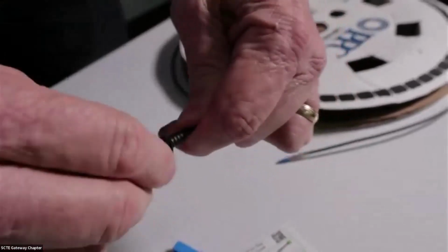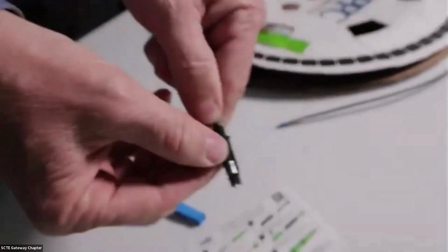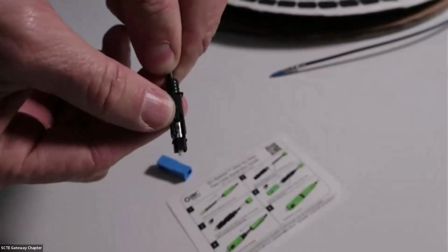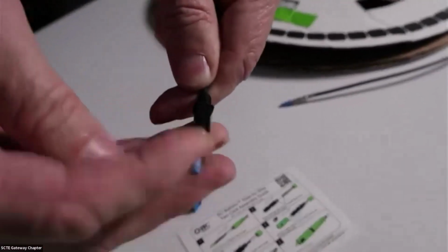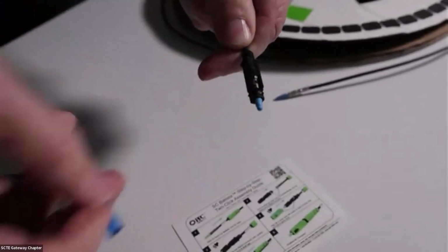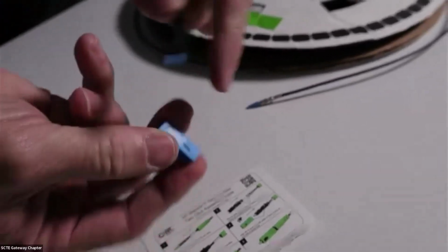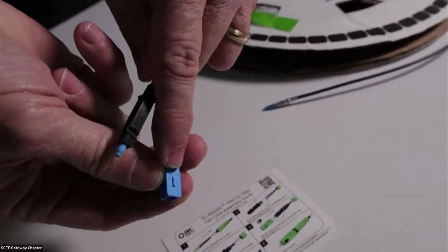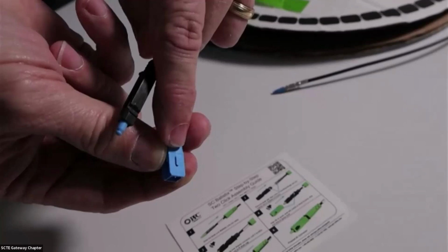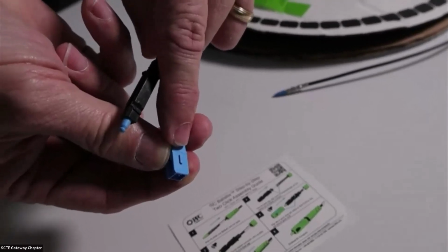Slide them on and push till you click. You can see the circle inside the window. That's showing up. Make sure you put the cap back on. Always got to protect the end of your fiber. The next is the front body. There's a little keyway on all SC connectors that shows the orientation of how it goes into the bulkheads, right?